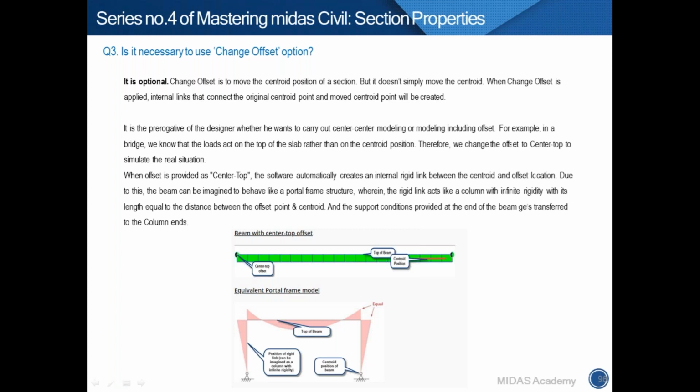So when designers build a model, they might have some assumption, like to ignore extra forces because they are too small. So change offset modifies the boundary condition and structure condition. They might face unexpected results depending on their modeling state. So therefore, I would like to recommend using it case by case and checking the effect of change offset.